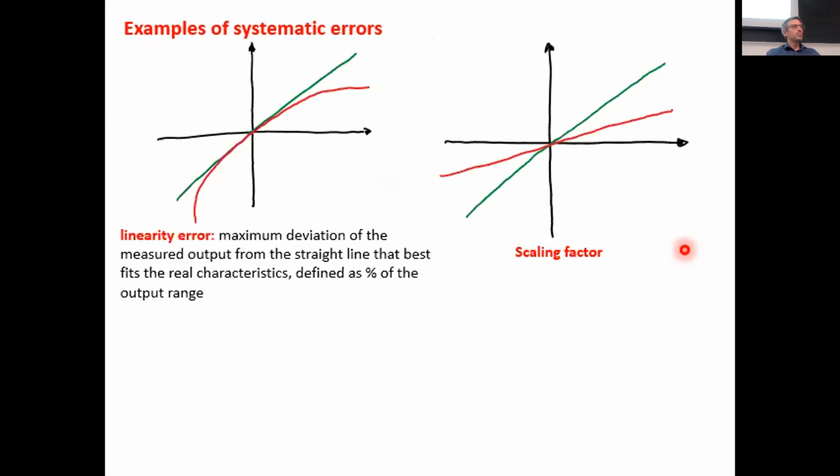So I need to estimate these gains with the proper calibration, adding weights, and see, okay, for 10 kilograms, I have 0.5 volts, 20 kilograms, I have 1 volt. Then I do this calibration for each force sensor, and then I will see the gain of each load cell to apply to the voltage that relates the force I want to measure with the voltage.